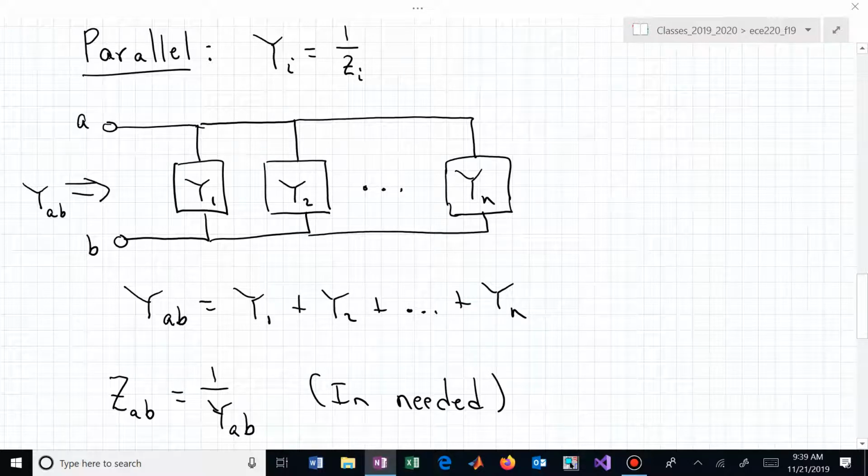And we're actually going to find admittances from impedances so that we can combine some parallel branches and make our analysis a little cleaner or easier, since we will just be adding and not having to worry about this product divided by the sum, etc.